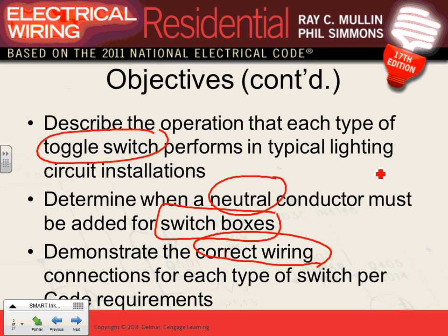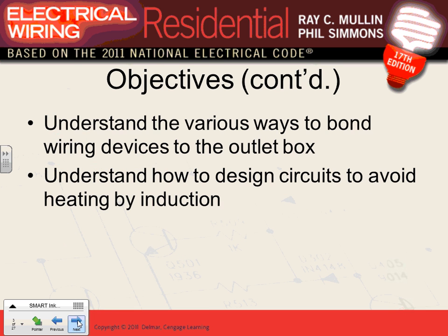So they're doing away with California three-ways. Yes, that's going to kiss goodbye a lot of wiring that we used to do. There are some exceptions though. If the walls are open, and you can fish because the top or the bottom of the wall is open, that's an exception. If all the wall is open, that's an exception. If you're wiring with conduits, that's an exception, because whether flexible or non-flexible, you can pull a wire. So that's the change that came in 2011.